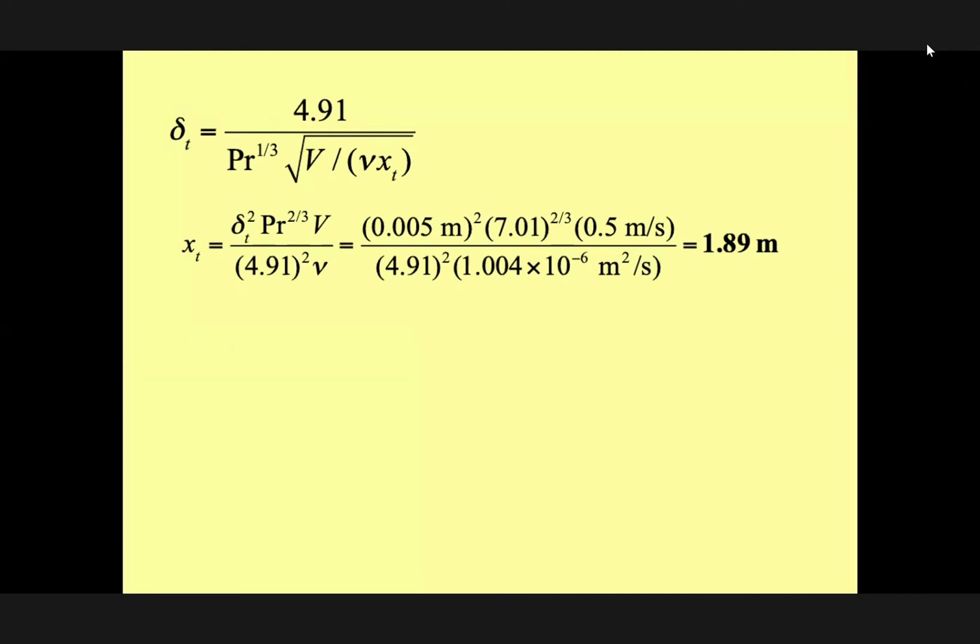And 90% of the time, my answer is wrong. How can I make sure this is correct? Can we use the PR? No. The only thing here is we made an assumption. When we use this equation, we made an assumption. What was the assumption? The flow is laminar. Excellent. Therefore, I have to go back and calculate if my assumption is correct.